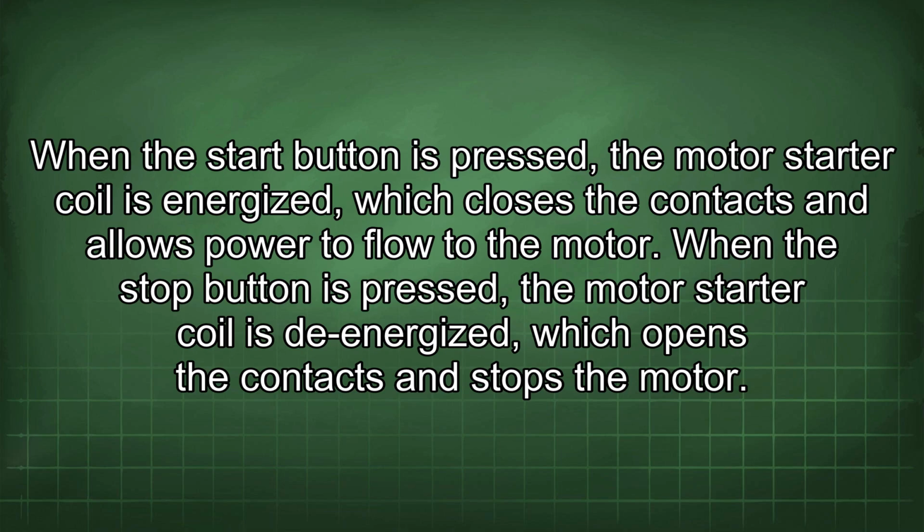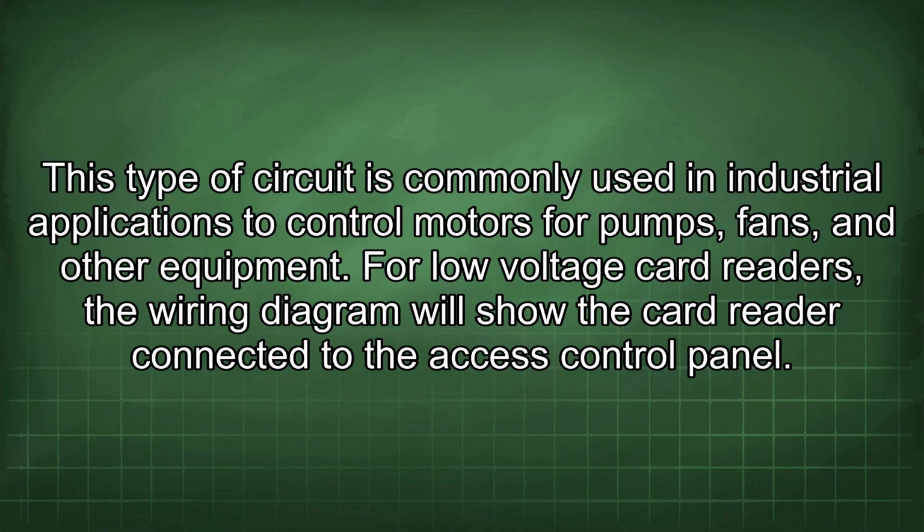When the start button is pressed, the motor starter coil is energized, which closes the contacts and allows power to flow to the motor. When the stop button is pressed, the motor starter coil is de-energized, which opens the contacts and stops the motor. This type of circuit is commonly used in industrial applications to control motors for pumps, fans,